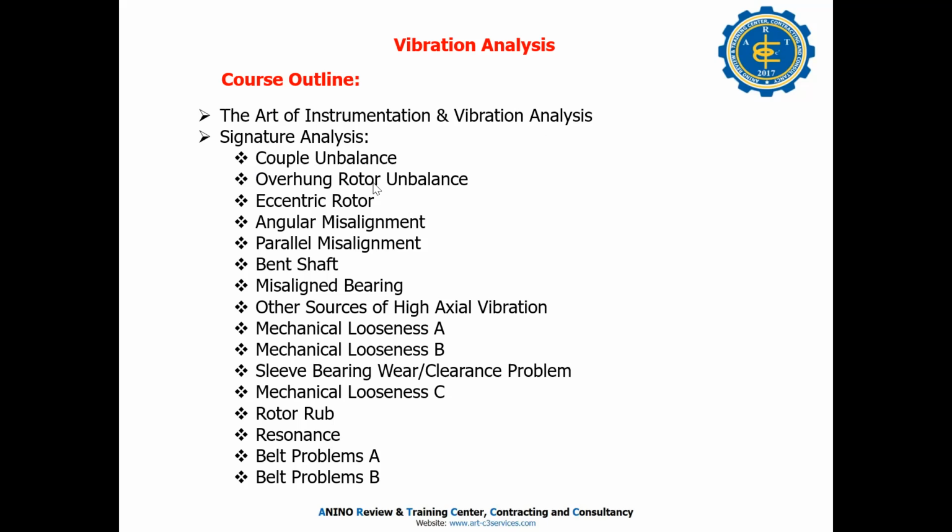You have the couple unbalance, overhang motor, rotor unbalance, eccentric rotor, angular misalignment, parallel misalignment. You have bent shaft, misalignment bearing, other sources of high axial vibration.